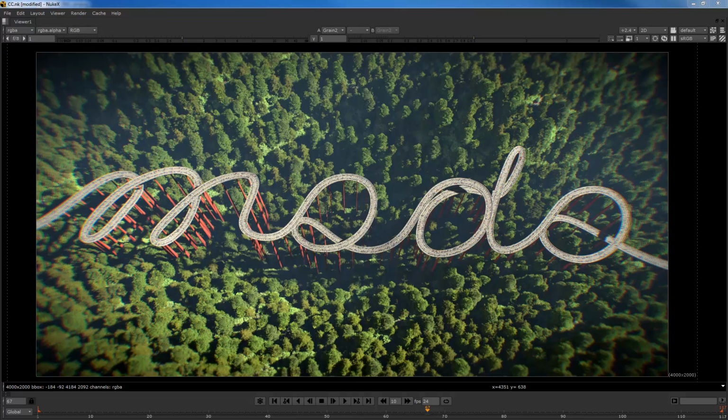And another question is that the speed of the render preview is so crazy. What is the machine he's using? I wonder about the specification of his computer. It is a stock MacBook Pro with 16 gigs of RAM, 4 cores, 8 threads. It is a powerful machine, but nothing really special. It is a notebook, really. So especially when you start playing with the render settings of your preview, if you decrease it to the bare minimum, Modo will just keep up with whatever you're doing, and then of course for the final you can increase it back.